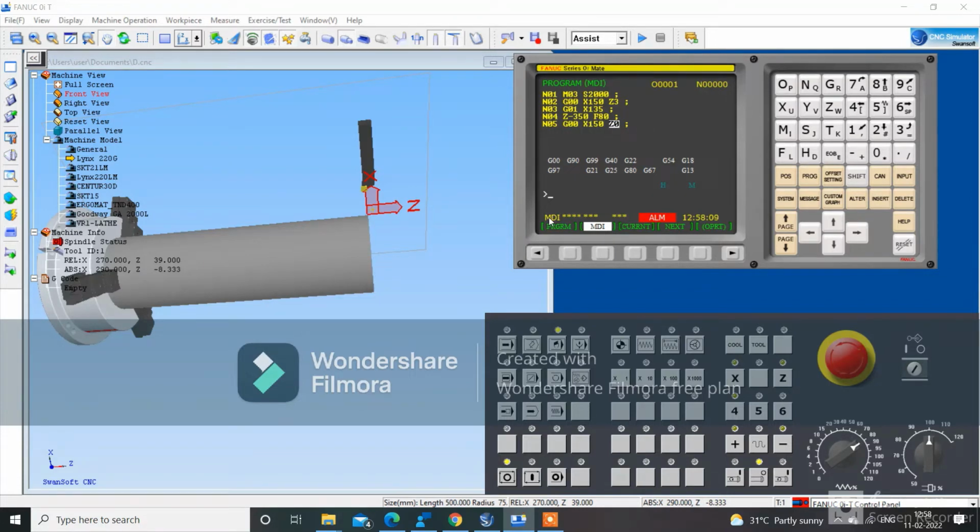Okay, fine. I'm not making it lengthy, I'm just typing the next few keywords too. See, the program is completely ended here. I'm just checking N01, N02, N03, N05, N06, etc. As you can see from the program, the diameter is given as 150 here, and it is reduced to 135, and finally the diameter is reduced again to 125.